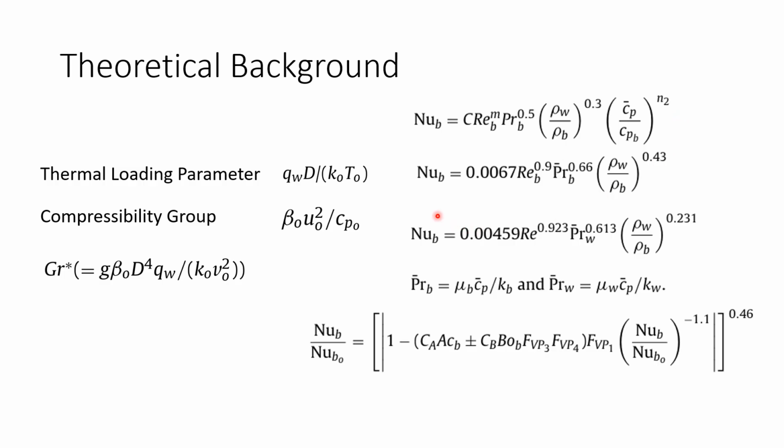For different fluids they observe these c values to be different and these n2 values to be different, and the final expressions which we get for the supercritical phase are also different from the normal Nusselt number equation which is used in forced convection. So the parameter values are significantly different from the forced convection Nusselt number equation.